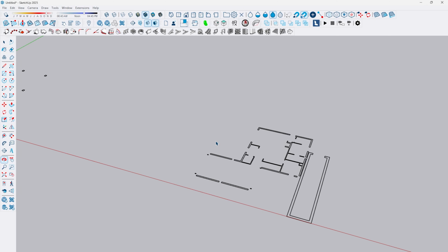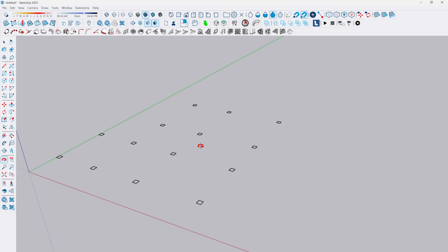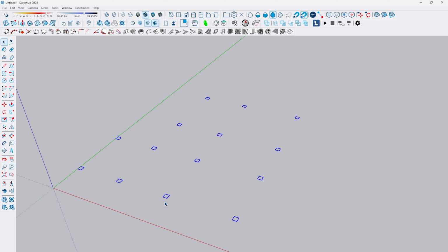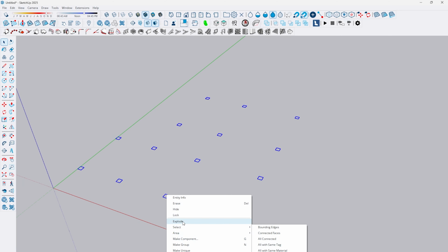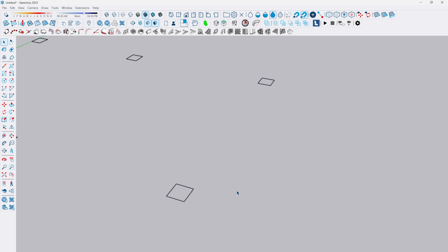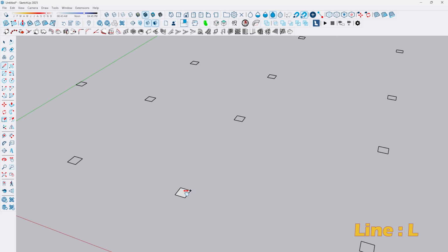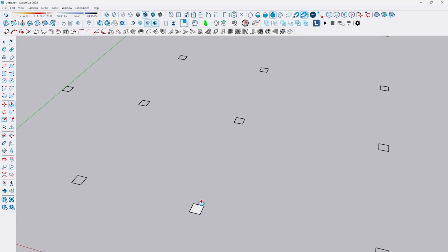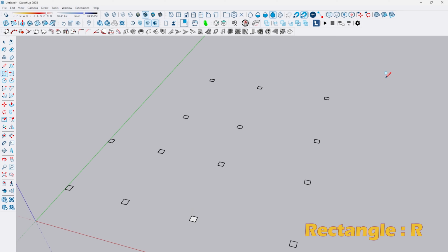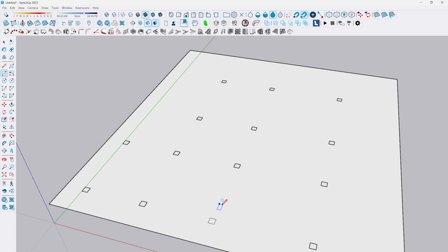Okay, let's first extrude the columns and lock them in place since they are often the least flexible part of your design. But since these lines don't have a face among them, in order to extrude, we need to create them ourselves by either tracing a line by the side of each column or drawing a rectangle engulfing them all in order to make a face on all of them in one move. Keep in mind, this trick could sometimes leave some of them out. So if that happens, just try the first option on them.